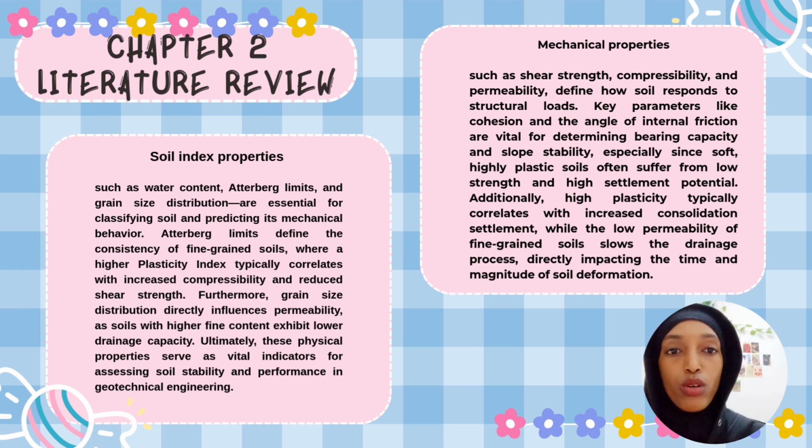If we move forward to mechanical properties, they describe how soil responds when subjected to loading. They include shear strength, compressibility, and permeability. They are critical for evaluating bearing capacity, slope stability, and settlement.